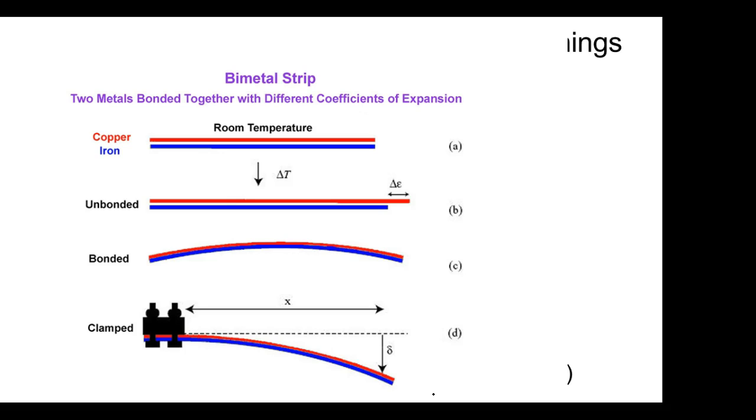This is why wires burn up and you have a short circuit. So you have a short circuit and your power supply can't regulate anymore, so its output voltage drops down. It's a regulated power supply. Regulated power supply means it tries to maintain a constant output, even though you're putting varying loads on it. Well, the problem is that it can only regulate over a certain range. So that means you've got your cruise control engaged on your car, and then you start up a 45-degree incline, that car is going to slow down. You understand that? Even though you've got that capability.